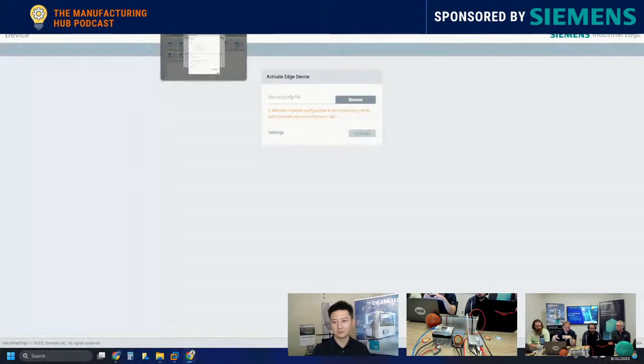So you're not going to have that traditional PLC rack with your I/O slices right next to the edge device, because at the end of the day, the edge device is just an IPC. But it's the operating system that runs on it that brings together all of the pieces to run the Docker containers and have everything be industrially hardened. When you tie in the management system, it allows you to control, manage, and update those IPCs that are installed on the factory floor.